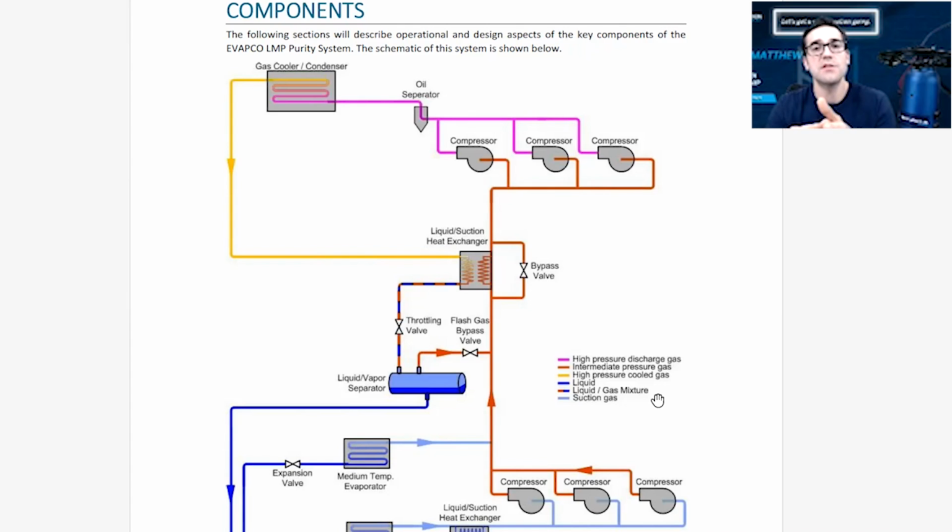So this is important because in CO2 systems, as we know, a lot of you have been here week in, week out, there are different pressures in the system. And as a technician, you need to understand this, because it's not like you just go to your tractor trailer and grab any pipe out of it and take it in and start piping it up. If you're going from the parallel rack up to the gas cooler and you're using high pressure pipe, it's not K copper. It's not K copper. It might be K65. It could be the Mueller style, XHB, whatever. But you need to make sure you don't mix that up, because this is happening out there.